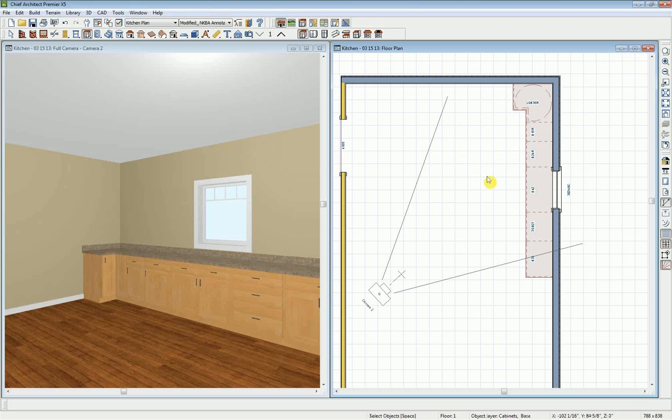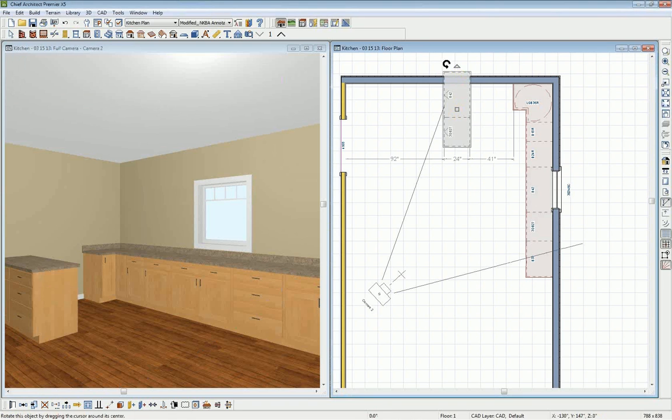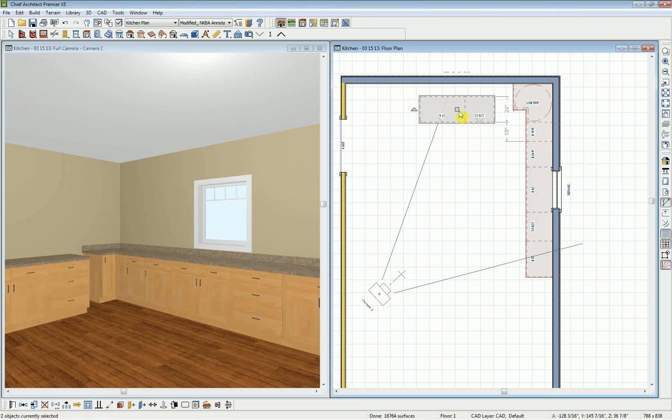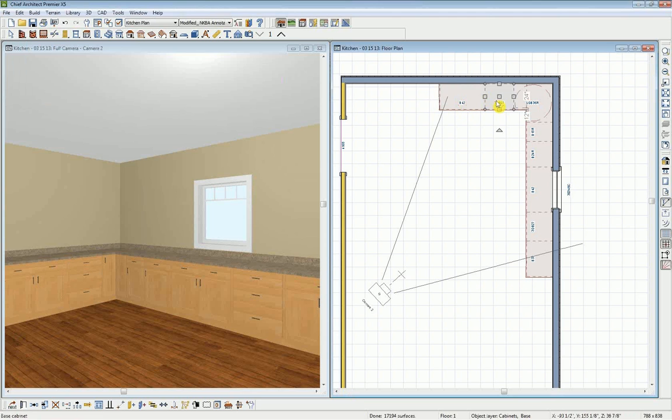Alright, so now I'm just going to copy and paste some of our existing cabinets. So first of all, I want to select my sink base and then our 27-inch cabinet. So I'm going to copy those. Since I've already modified those, it's pretty easy. We can just copy and paste. And I'm just going to rotate those around, bump them back to the wall and over to our cabinets. So we'll put a cooktop in our 42-inch cabinet on this side.